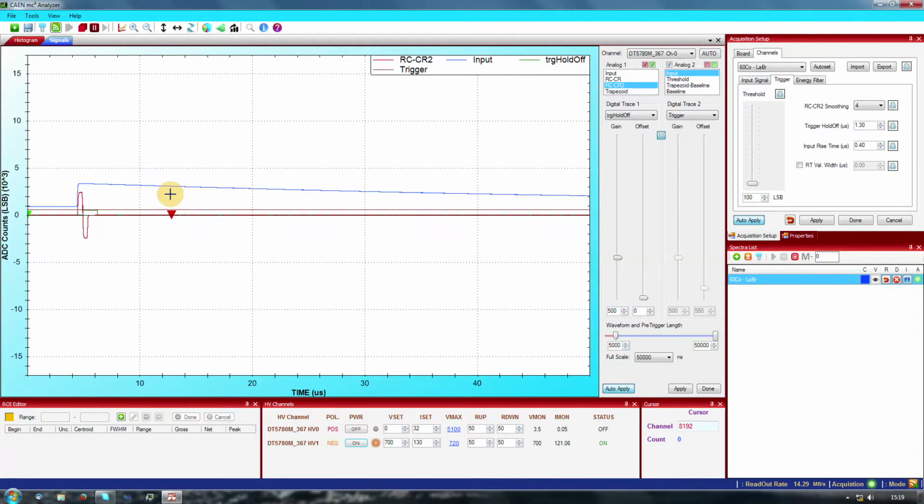The user can place two cursors in the Signal Inspector window. The red cursor can be moved with a simple left click on the screen. A green cursor can be placed or moved on the plot. The user has to press and hold the Shift button of the keyboard and do a left click with the mouse. These cursors are placed on top of one of the analog traces.